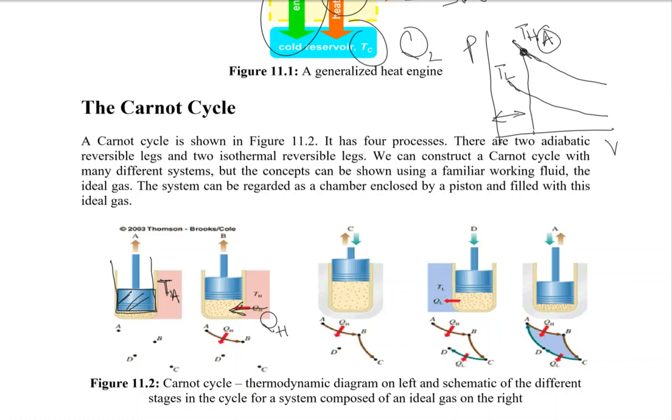In other terms, during the heat absorption there will be expansion of the piston. And we have already said in our conceptual Carnot cycle that the temperature of the system should remain constant. So when you are supplying heat, the temperature would remain constant, there would be heat absorption, and there would be expansion in the piston and cylinder arrangement.